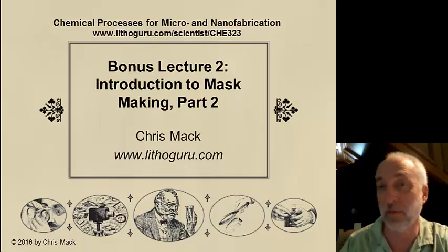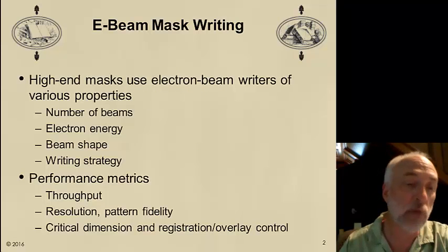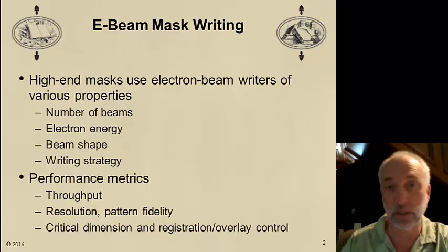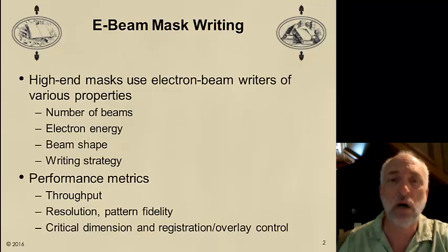I mean, not a terrible amount of detail, it's a complicated subject, but we're going to talk about mask writing with e-beams. Now, we can write masks with lasers as well, but those are for lower resolution applications. All of our high-end masks today are written using electron beam lithography.